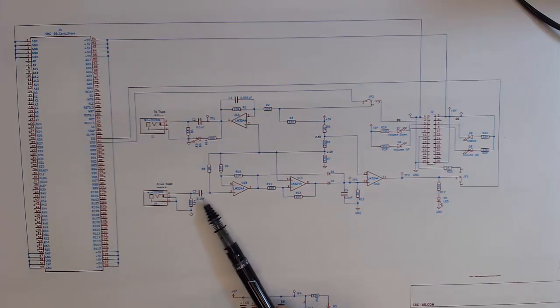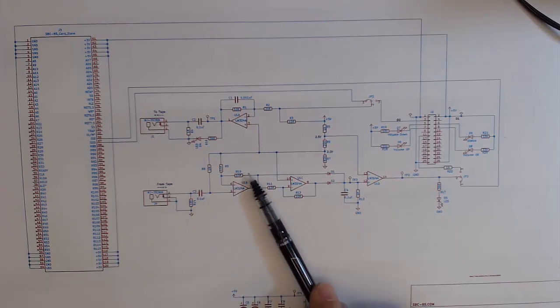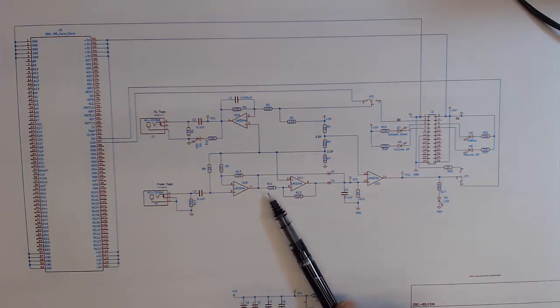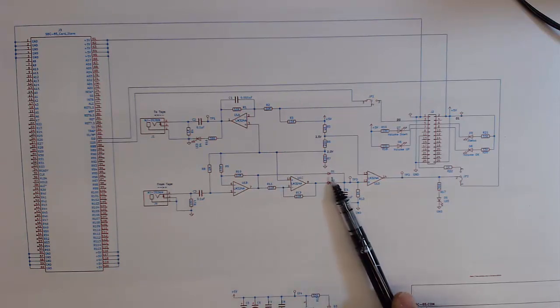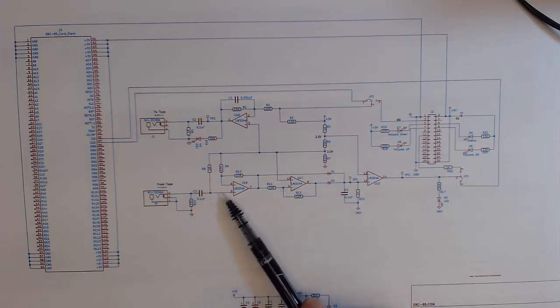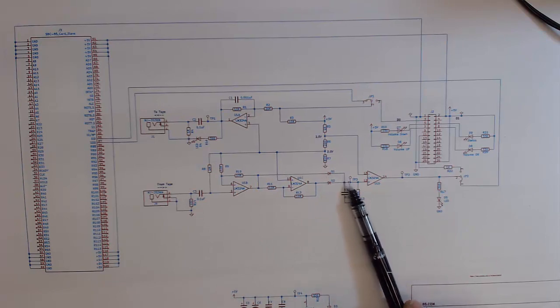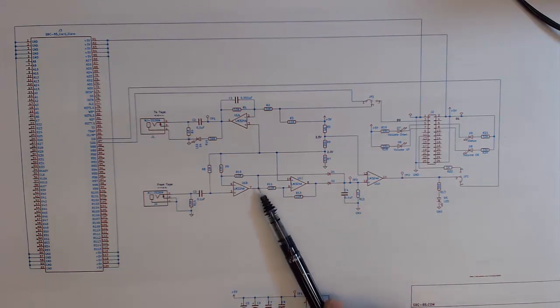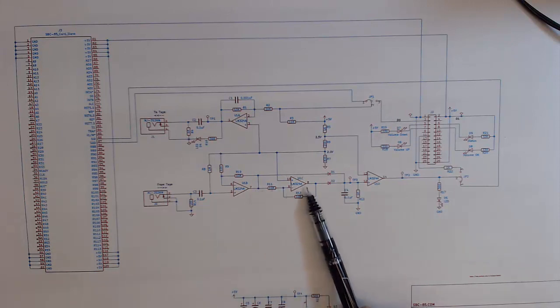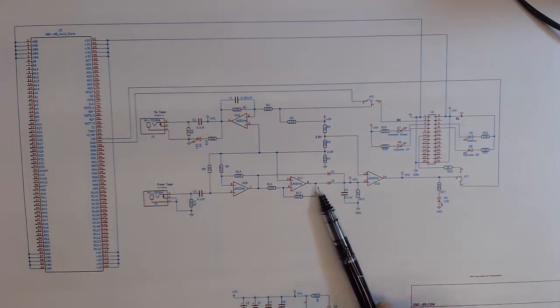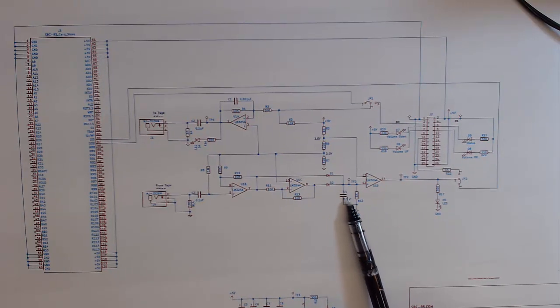Now when we come into the tape, this is AC coupled. We come into this first amplifier, which has a gain, and it buffers it up to this line, but we can see that this also goes to this signal diode. So when it comes in and this is on the positive rail, this is forward biased, and so it charges up this capacitor faster than this little resistor right here is discharging that capacitor. Then when that AC swings low, this inverting amplifier is now at the rail, and so it's forward biased on its diode and charging that capacitor up.